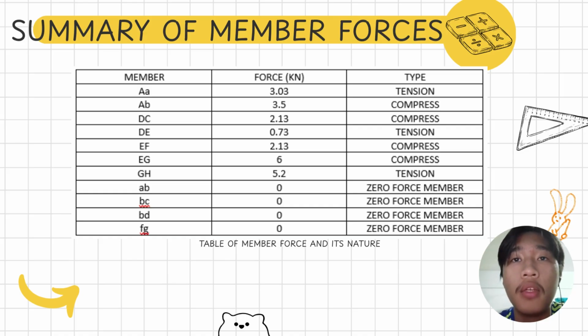Starting with members under tension, we can see that member AA carries a tensile force of 3.03 kN, while member DE carries 0.73 kN in tension. The highest tension force occurs in member GH with a value of 5.2 kN, indicating that this member is being pulled significantly.